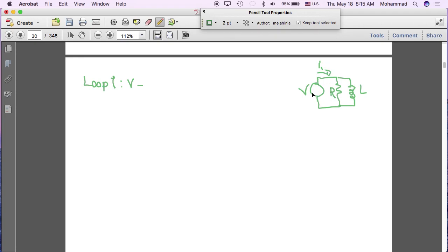Okay, but that loop doesn't have a single current. Can you see that? In the first portion of it, there is current that comes from the source of voltage, but that current is split. So I agree that there are two currents, but we need to name them so we can defend our decision. If you call the current coming out of the source of voltage I1 and the current going through the second portion I2, then what goes through the middle one is I1 minus I2.